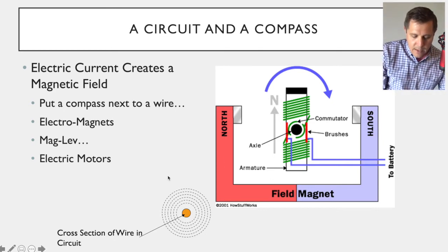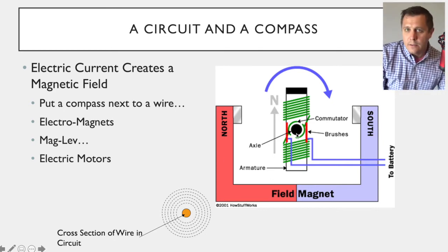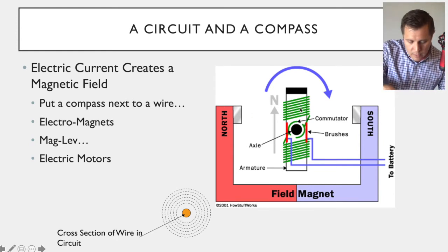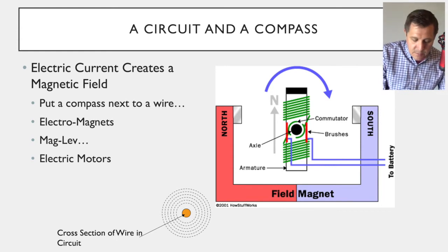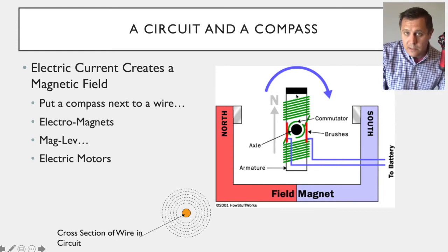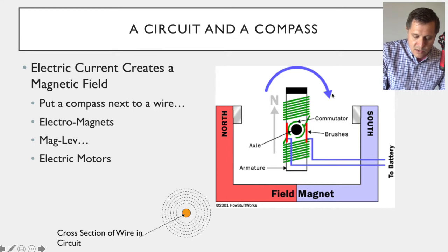Well, what they figured out is if I put little gaps in the wires, as soon as that north is supposed to get to the south and it would normally stop, we're going to turn off the electricity. And what the magnet would end up doing is, or the inner part of the magnet would keep spinning. It's got some momentum to it. It's spinning. We got angular momentum. So it would spin a little bit past that south.